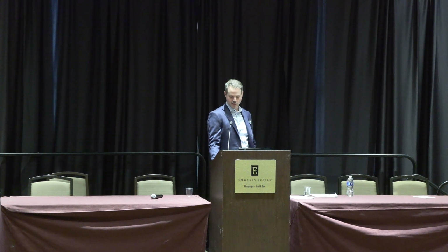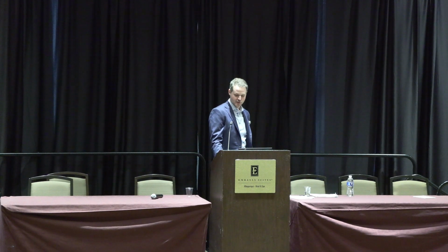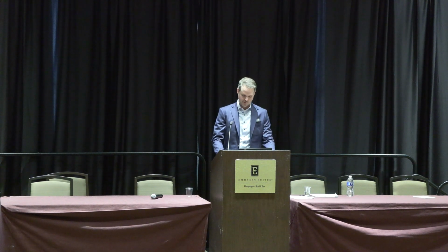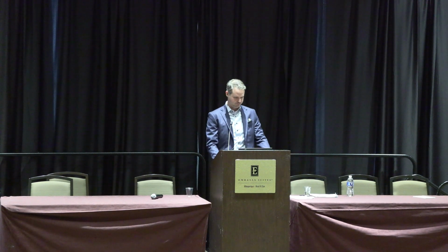It does have some limitations still. It can't see past obstructions, so much like shining a flashlight in a dark room, which is the analogy we usually give, it will create shadows. If it's mounted to a vessel, it has trouble seeing things like undermining due to the angle of attack of the sonar beam. It can't see under things. I'll talk more about that in later slides. And it does create large amounts of data that can be cumbersome and time-consuming to process. So it's something to be aware of when you're using multi-beam.